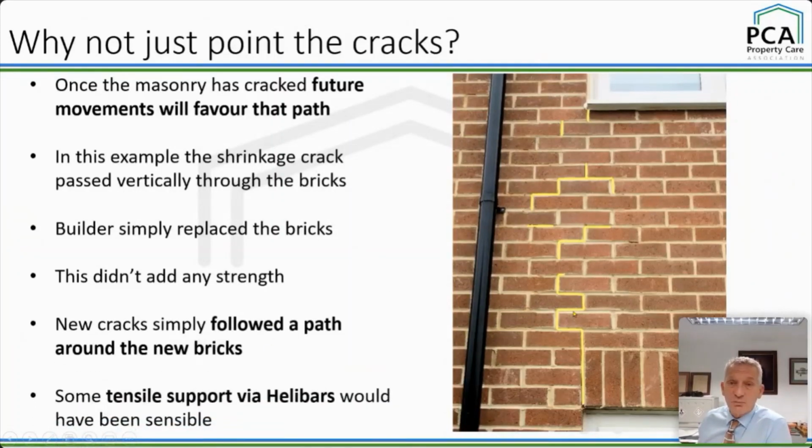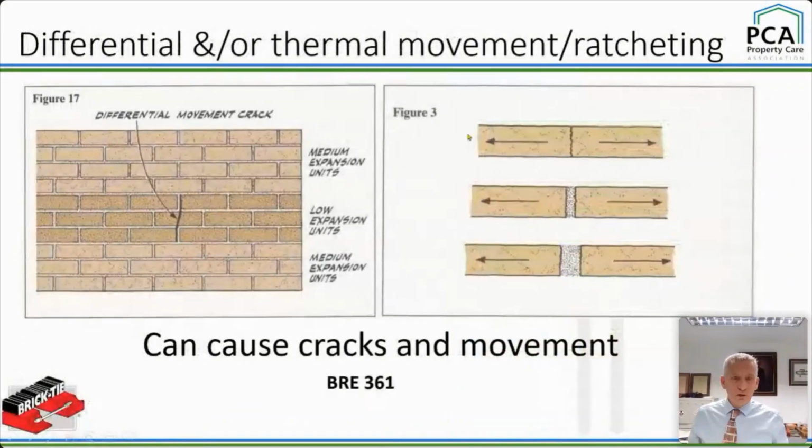Some tensile support with some Helifix bars or similar, other flavours available, would have been sensible there, as well as sorting the movement joints out. Now then, get a copy of BRE 361 because it's a good document. I recommend you all download it. I don't think they'll sue me for using a bit of it. I think you're allowed to if it's for teaching.